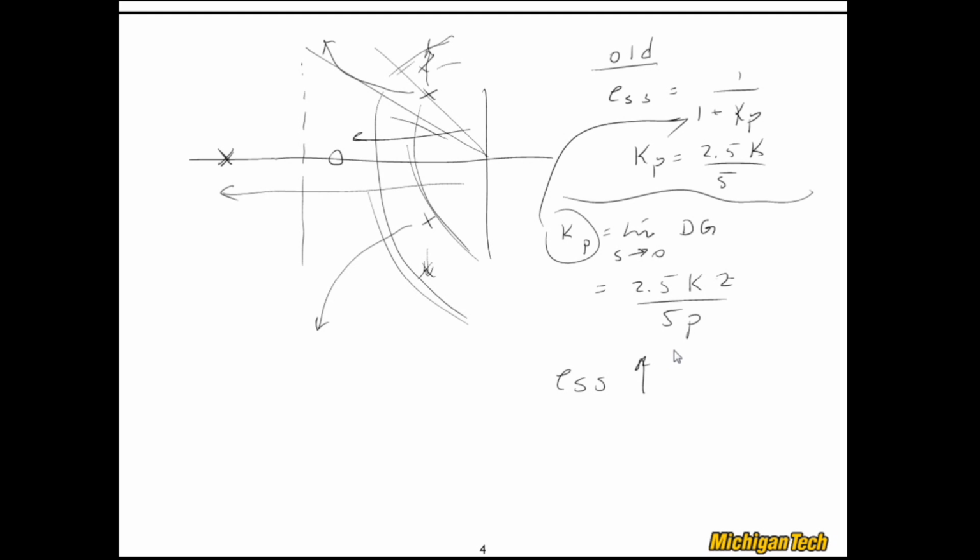Another thing to be aware of, if you look at this messy sketch right here, is that as these poles are heading off like so, this closed loop pole is heading to this k equals infinity point. The impact of that is that these poles may no longer be dominant. That is, this pole may be sufficiently close to these poles such that I can't just always use the second order time domain type relationships to do the design.